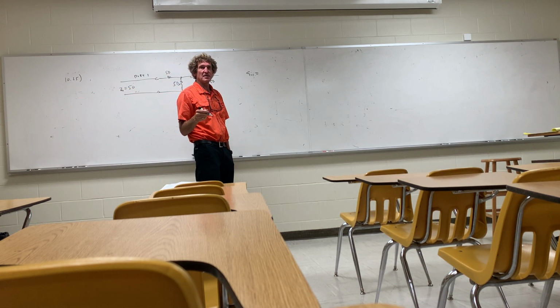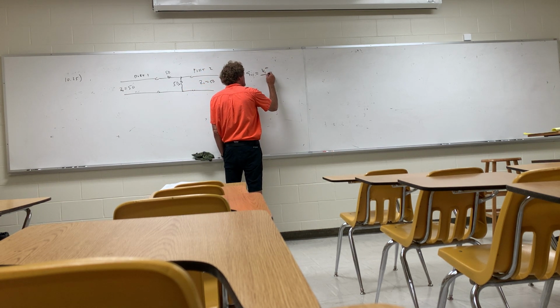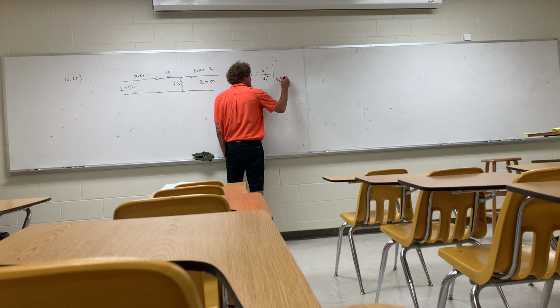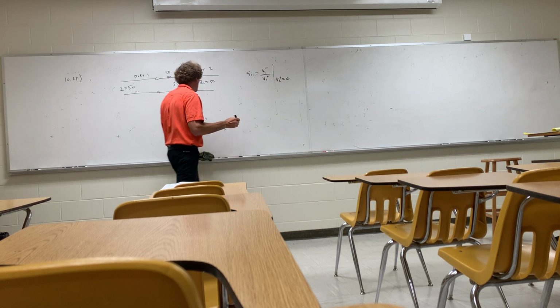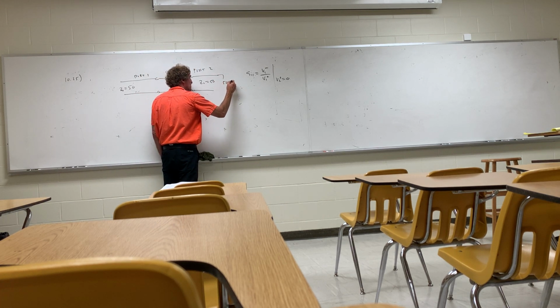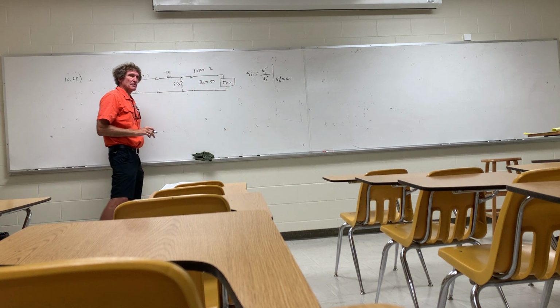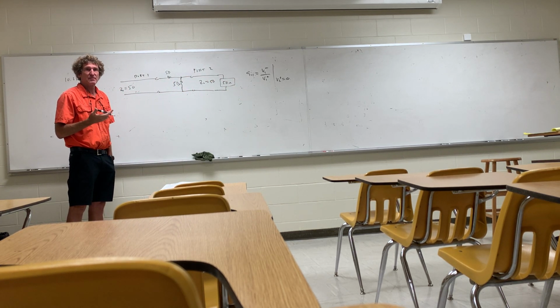Now, I know you've just been introduced to this, but S11 is what? It's V1 minus over V1 plus, assuming what? V2 plus is 0, right? In other words, it's matched. So I'll just put this for the betterment of everybody. I'm going to put 50 ohms here. So in your mind, you know that nothing is reflected back into port 2. I'm just doing that for a mental thing.